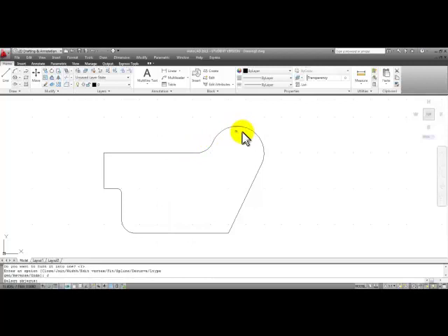You can select each one individually, or you can pick in space and pull your mouse across all the objects, selecting all of them to join and then enter. It should say in your command line that 9 were added. We're done editing the polyline. We can press enter to get back to the command line.